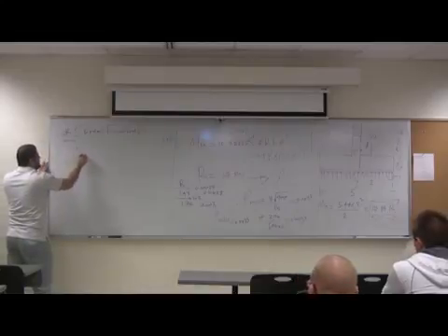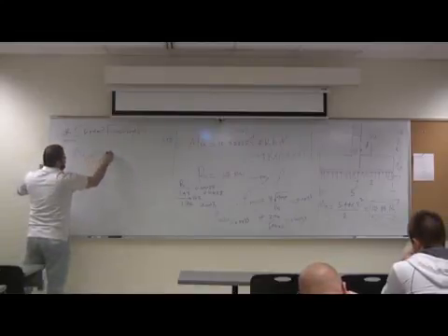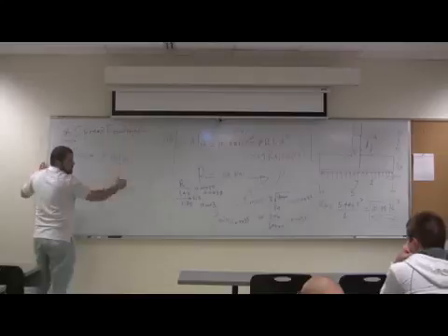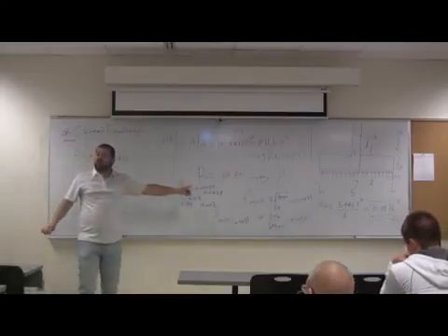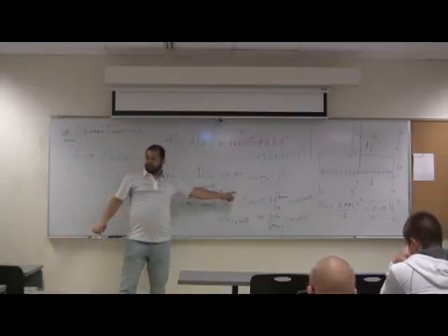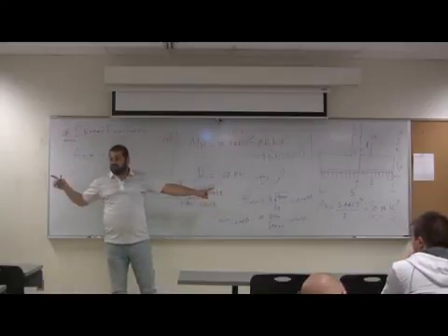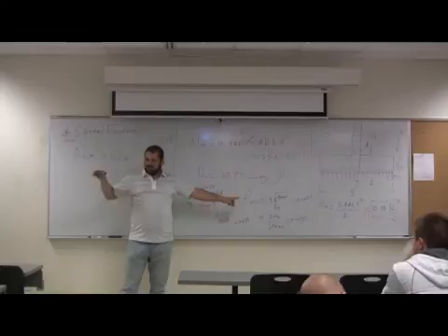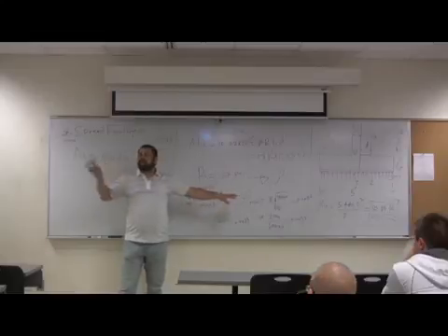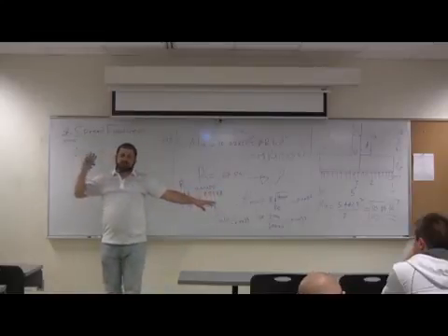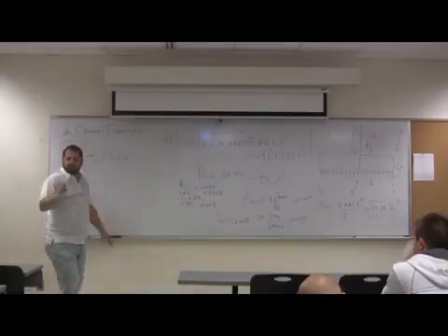AS equals what, guys? Rho times B times D. Anytime you calculate rho, this rho is calculated based on strength. It's not the shrinkage and temperature. To calculate AS from this rho, you multiply by BD. For the shrinkage and temperature, you multiply by BH, which is A gross.